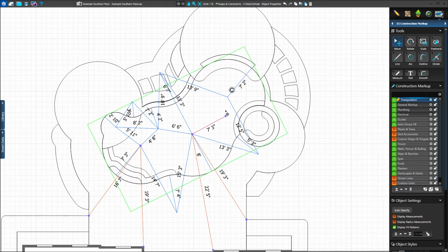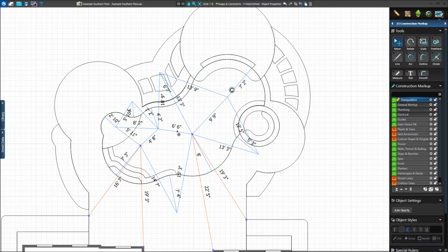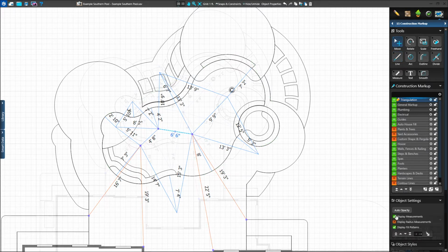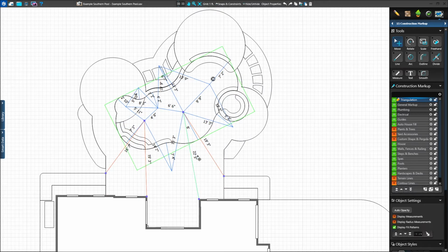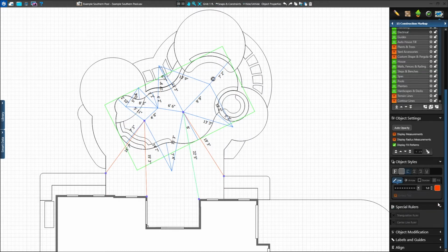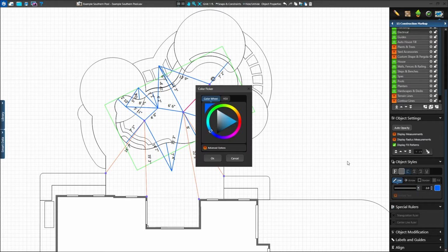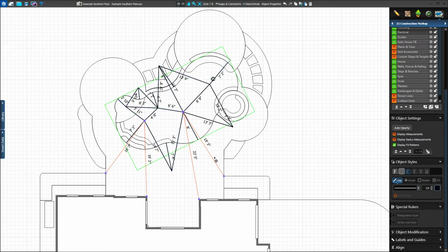We can select them, move them, and delete them as well. We can also draw new lines if we want to display any additional measurements. We can adjust all of the line styles and colors as well. With an anchor selected, adjusting the line setting will adjust all anchor lines. The same will happen when adjusting the lines connecting all of the radius points. All matching line types will be updated at once.